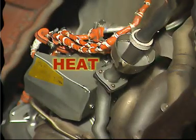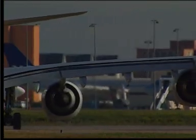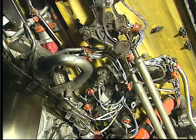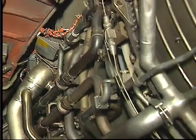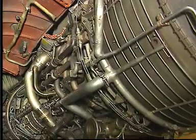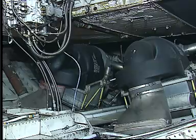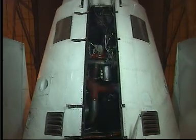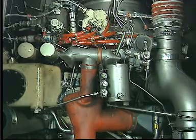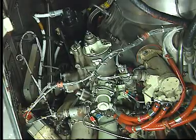Heat may result in the degradation of electrical items. Wiring exposed to high heat over a long period of time can accelerate degradation, insulation dryness, and cracking. Engine and air conditioning packs, as well as ducts, are potential damage sources for wires due to the heat environment. Electrical installation in the APU area, such as wiring, terminals, and connectors, are also exposed to heat.